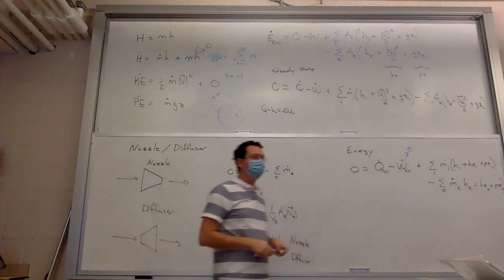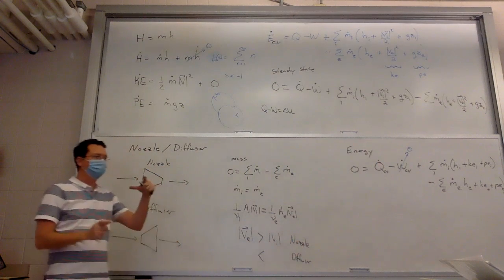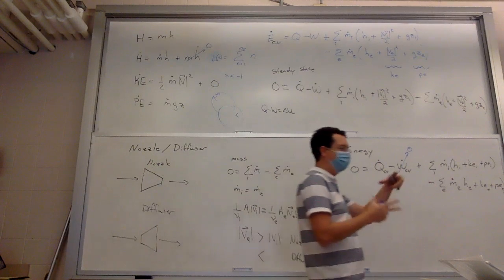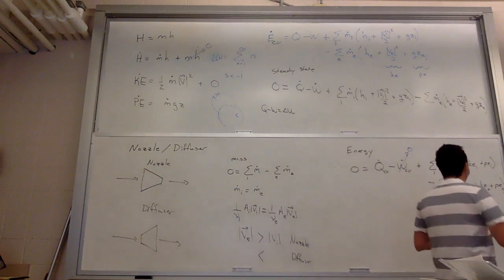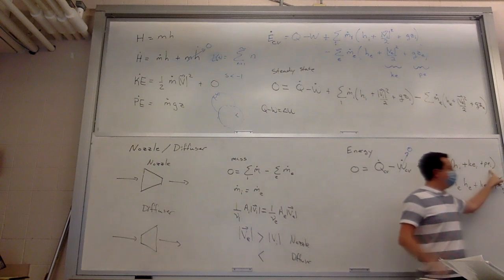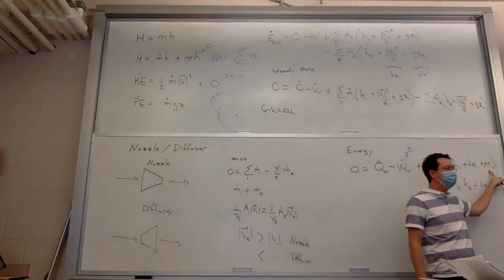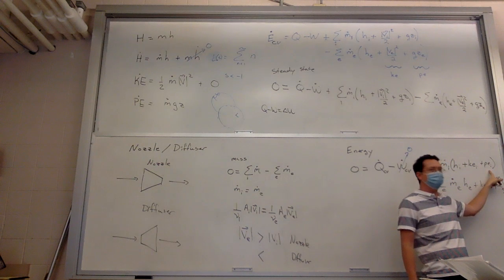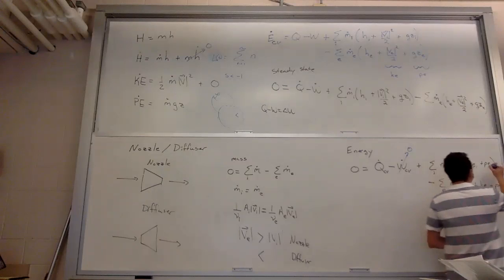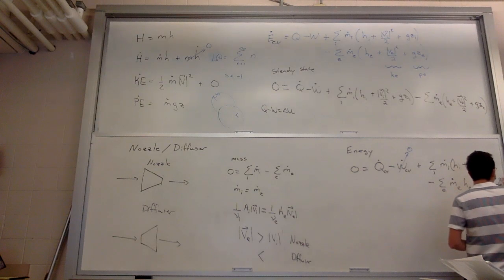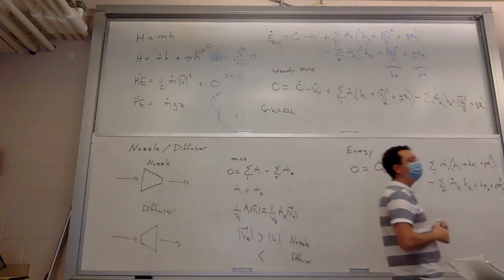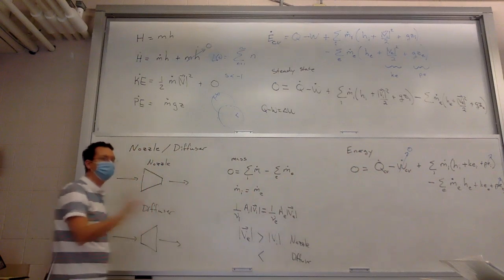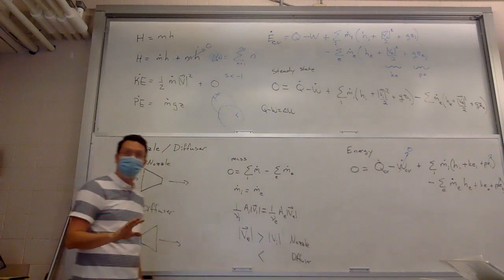How big is a nozzle? Make it as big as you want. Okay, but in real life. Is it 1,000 feet deep, like a deep oil well, a single nozzle that goes all the way to the bottom of the ocean? No. So the potential energy is going to be negligible. You just don't worry about it. The change in potential energy is negligible. You can just drop those terms relative to everything else in the problem. Okay?